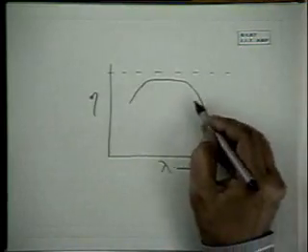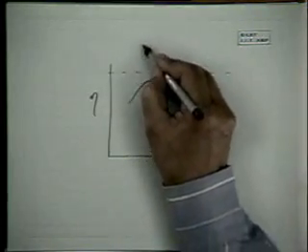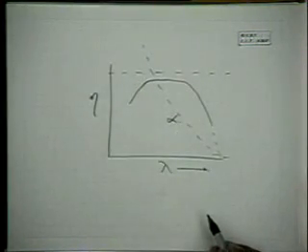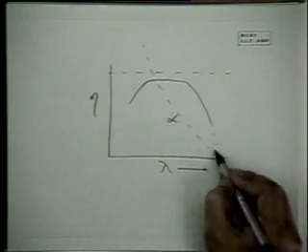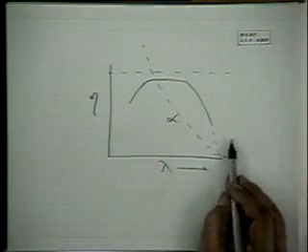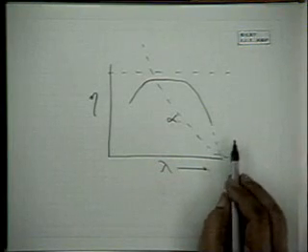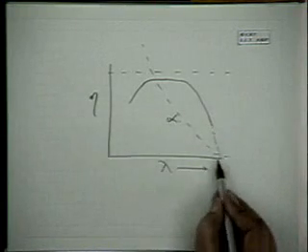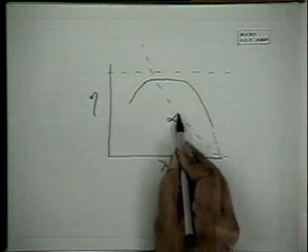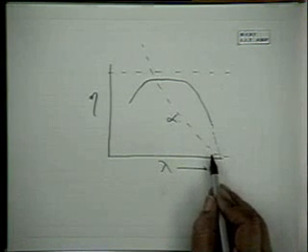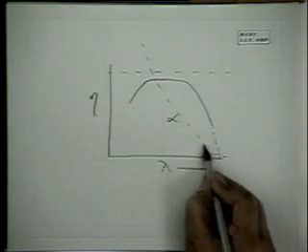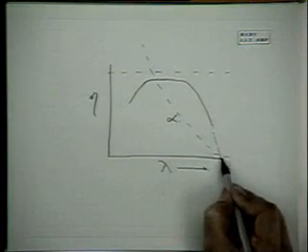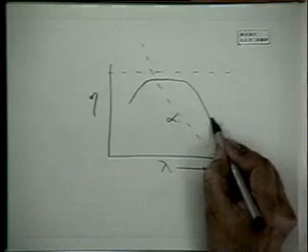And alpha goes something like that, which is known. So we plot this part of the spectrum, where alpha is increasing slightly, so 1 by alpha is decreasing. This is near the band edge, and the quantum efficiency is increasing.